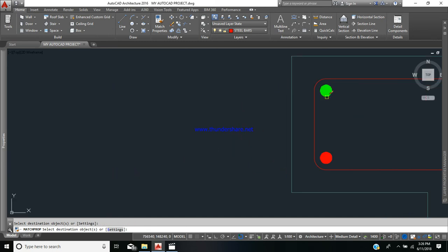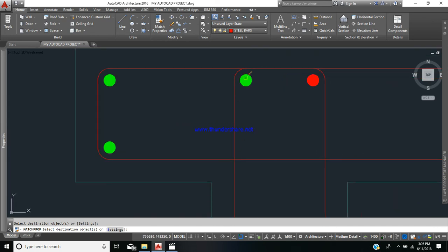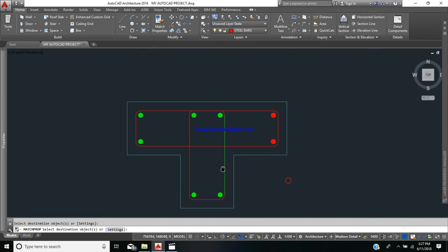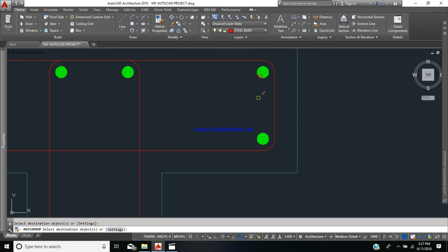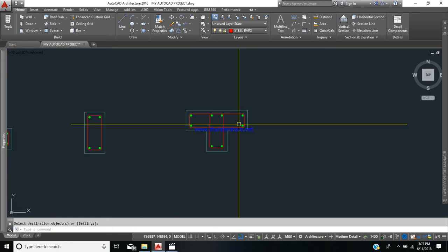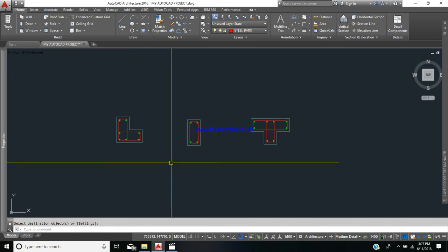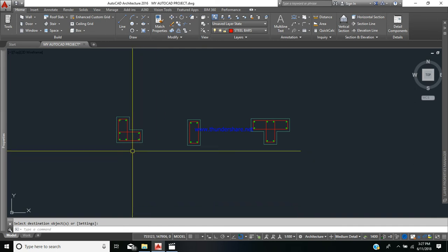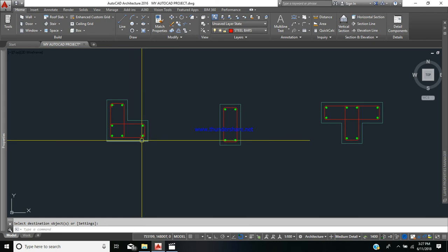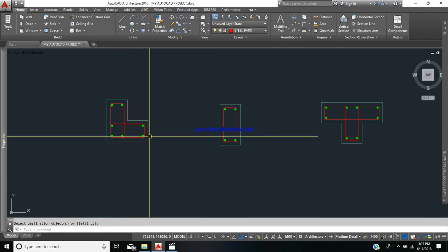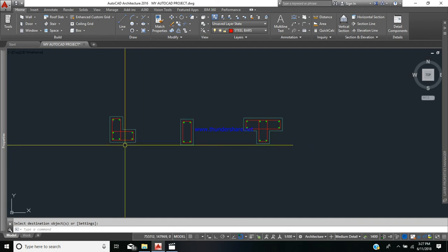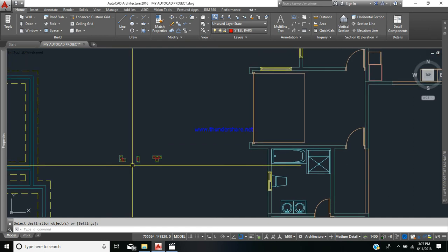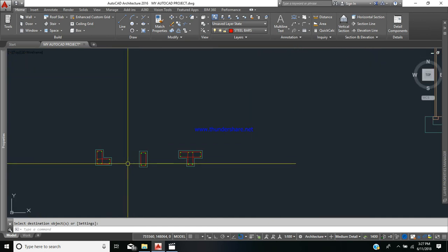Alright. So I'm painting all my vertical bars, which are represented as circles. Alright, let's give an enter. And I would now have all three stiffeners being adequately represented. For use, however, again, it's going to be hard for installation if the stiffeners are in pieces. And so what I'm going to be showing you is how to make these into a block. If they are in a block, they can be more easily selected for insertion.